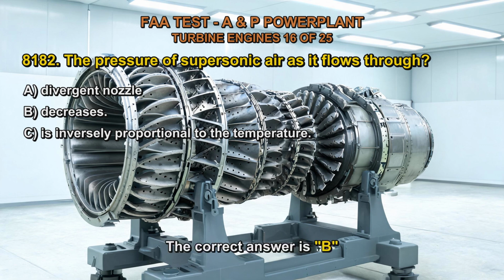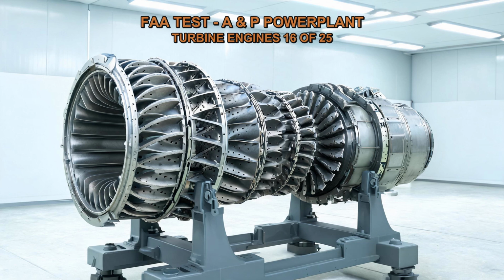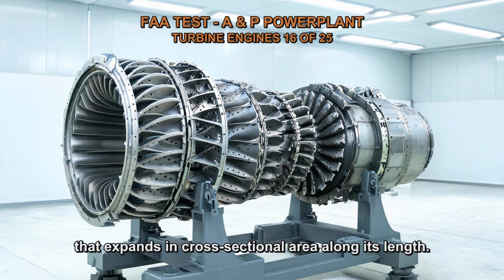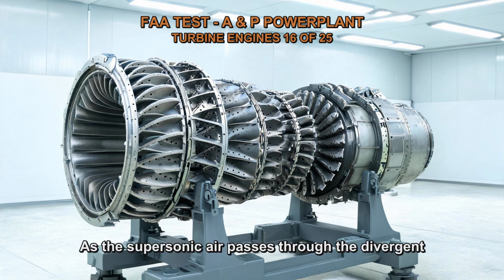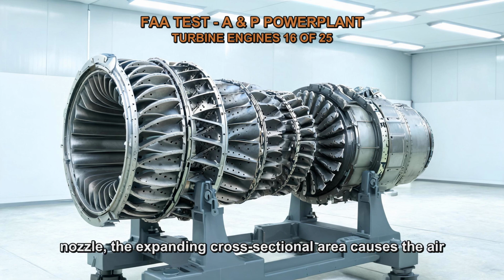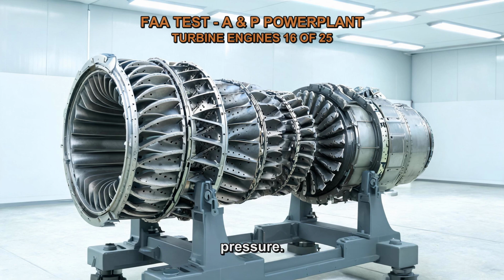The correct answer is B. When supersonic air flows through a divergent nozzle, its pressure decreases. A divergent nozzle is a duct or passage that expands in cross-sectional area along its length. As the supersonic air passes through the divergent nozzle, the expanding cross-sectional area causes the air to further accelerate, resulting in a decrease in pressure.